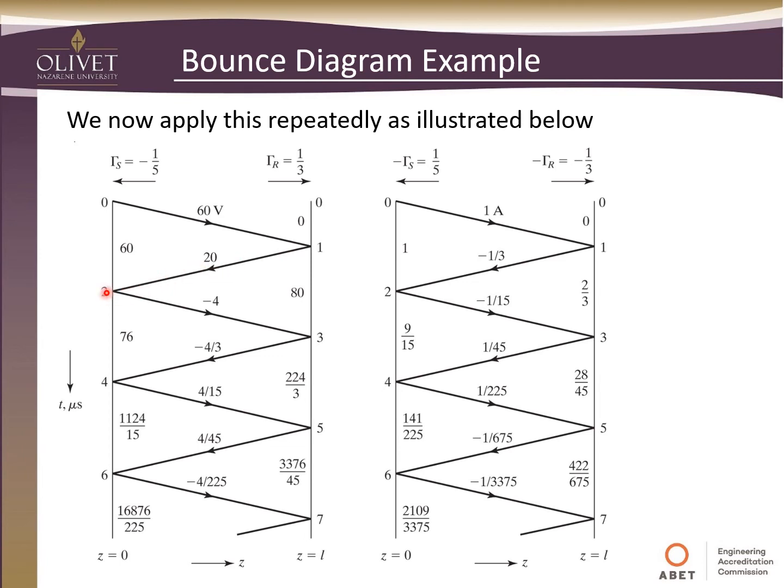Okay, so again, we have another microsecond going by, this 20 volts is going down, then bang, at 2 microseconds, it reaches our source. So at this point, we have the reflection coefficient negative 1/5. So negative 1/5 times 20 is negative 4. Okay, so now the voltage at the terminals where our source is going to be the addition of all of these.